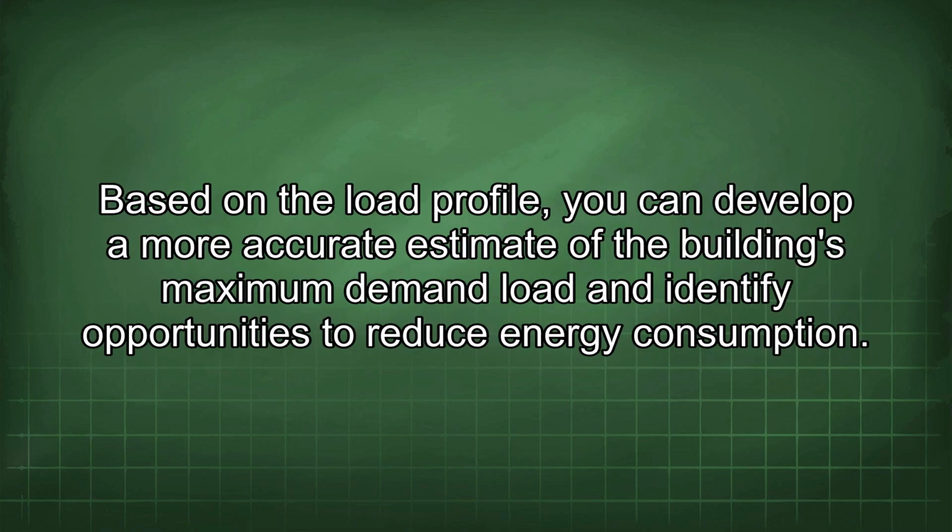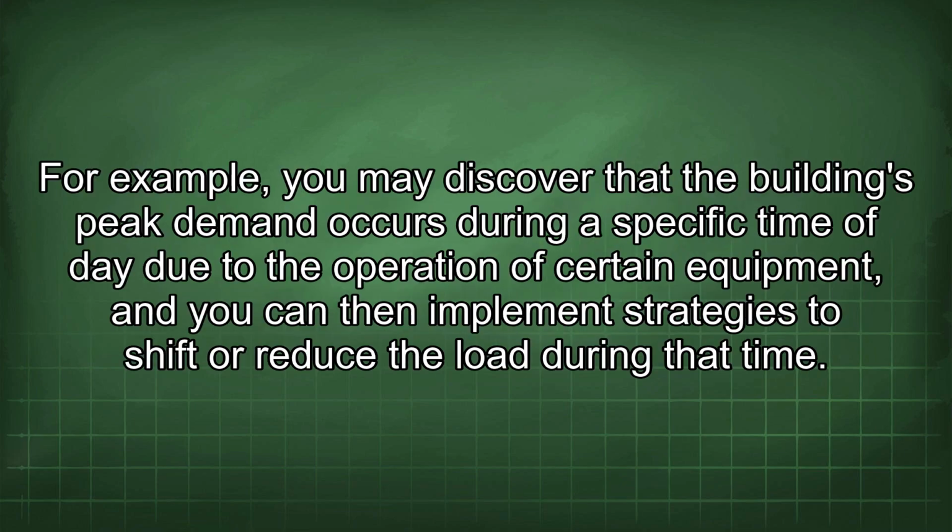Based on the load profile, you can develop a more accurate estimate of the building's maximum demand load and identify opportunities to reduce energy consumption. For example, you may discover that the building's peak demand occurs during a specific time of day due to the operation of certain equipment, and you can then implement strategies to shift or reduce the load during that time.